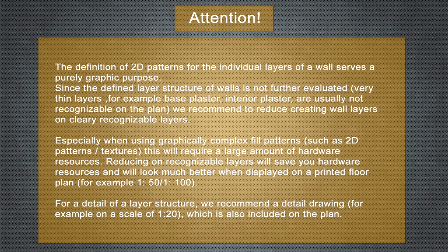Especially when using graphically complex fill patterns, such as 2D patterns or textures, this will require a large amount of hardware resources. Reducing unrecognizable layers will save you hardware resources and will look much better when displayed on a printed floor plan. For a detail of a layer structure, we recommend a detailed drawing, which is also included on the plan.